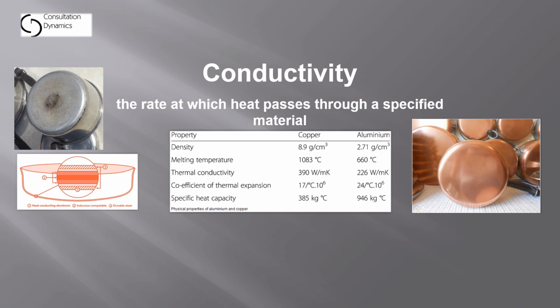Now, there's another type of cookware we see a lot of today where the aluminum is sandwiched in between two layers of stainless steel, and this is for cooking with what's called induction cooking, induction ovens or induction hot plates. This is where there isn't really a flame and it's not an electrical coil that heats up, but through the process of electrical induction, the pan itself actually heats up. In order for that to happen, it has to have a ferrous material there that the inductor is reacting with, and that's where the stainless steel comes into play. But sandwiched in between the layers of stainless steel is a layer of aluminum so that it spreads the heat evenly to the sides of the material.